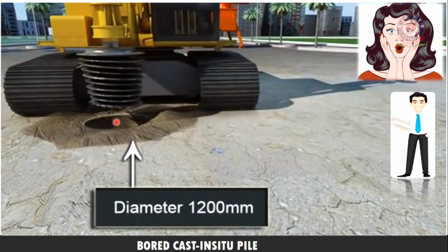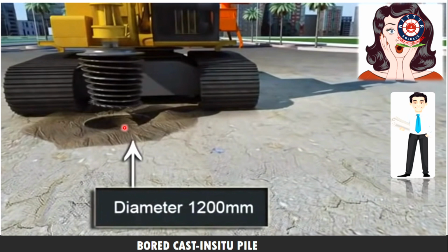If the soil is weak as per the soil report, till that depth, like 1 meter or 2 meter or sometimes 3 meter, we put the casing, then we start boring. If you do not put the casing, the bore starts collapsing when you start boring. So to avoid that collapsing, you use the casing.